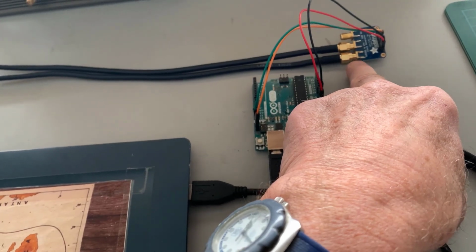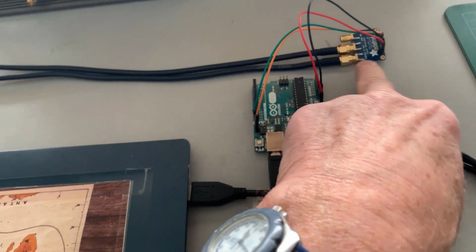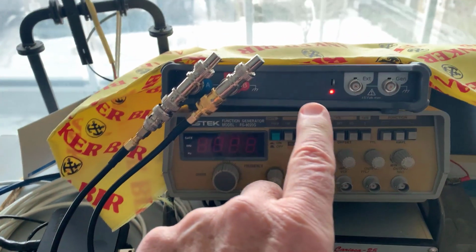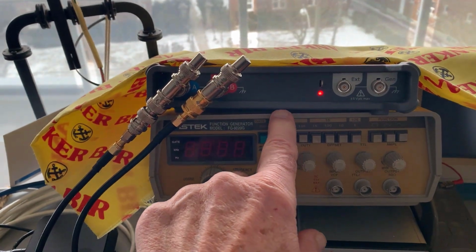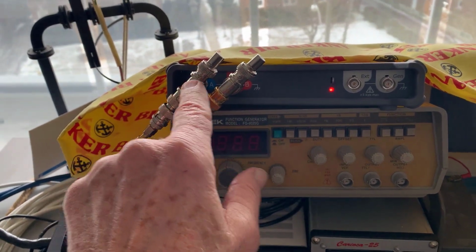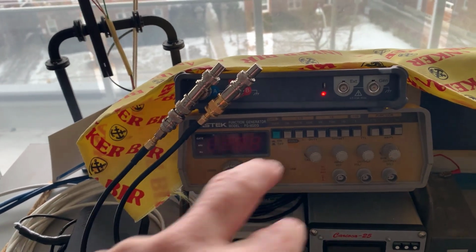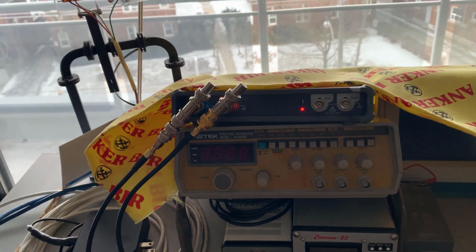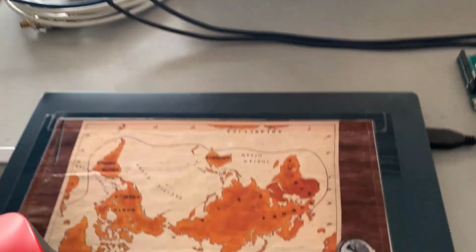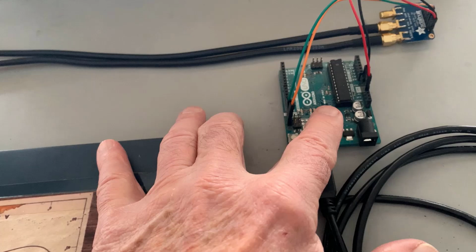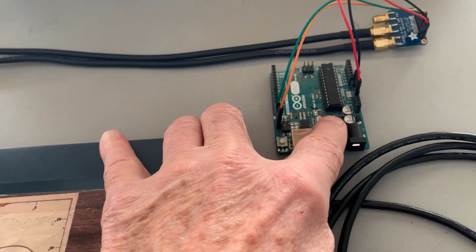And I've got coaxial cables on clock 0 and clock 1, and they go to a PicoScope, a digital USB scope. And notice I've got them terminated in 50 ohms because they're transmission lines. So I'm going to look at it on the scope and the spectrum analyzer, and we're going to compare that to the simulation. And the dev board is connected to the Arduino Uno.